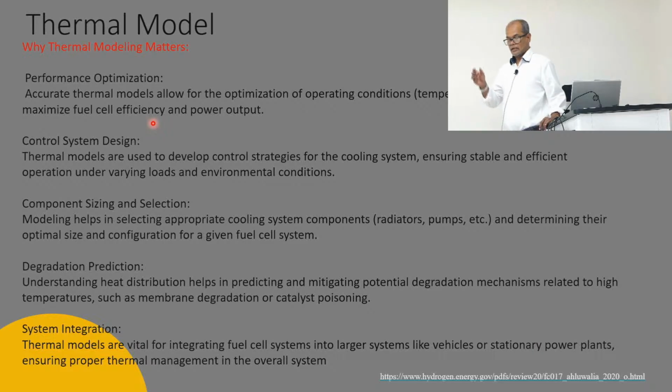So let's say you have the fuel cell in a system where the weather is cold, and somewhere else you place the fuel cell where it has hot weather. If you want to make sure it works for different temperatures, then you need that model in your control system design. But if you think that the temperature will not change that significantly, then it's okay to neglect it.